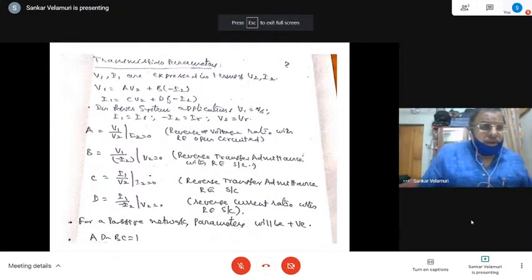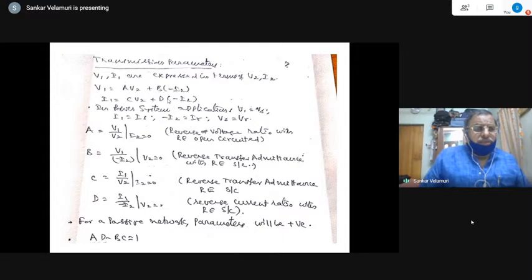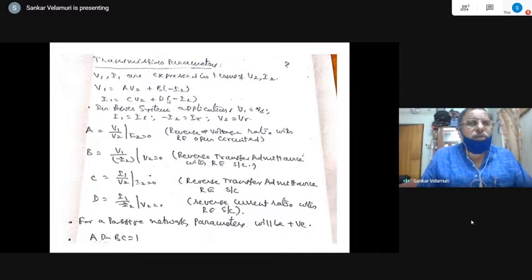Okay. There is only one doubt that has been raised previously. In the problem that is being stated, -8 into I2 minus I1 has been taken because I1 and I2 are the loop currents considered in clockwise direction in each of the loops. So according to Maxwell's circulating current theorem, it is the algebraic sum of the currents that we have to take for that particular loop.